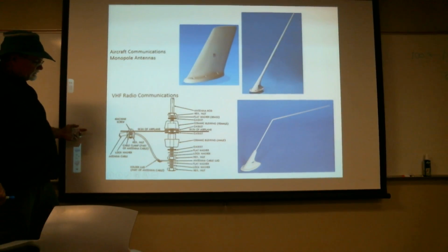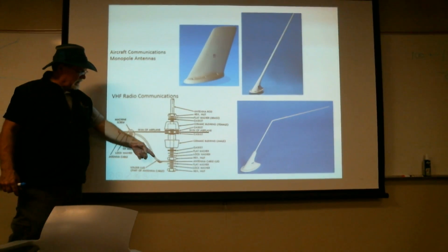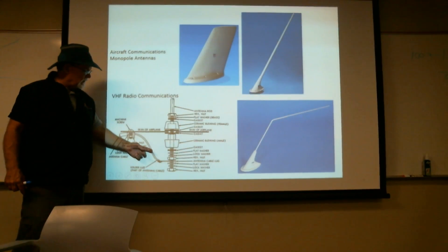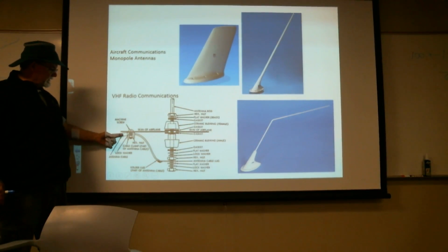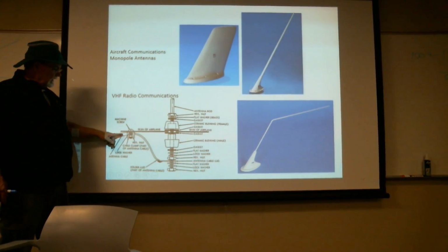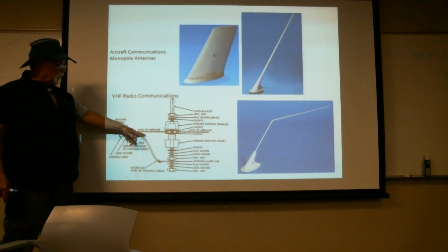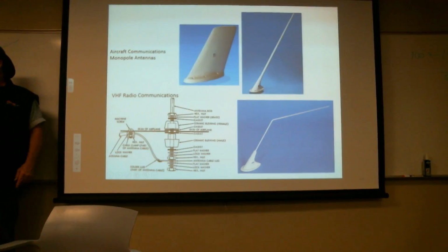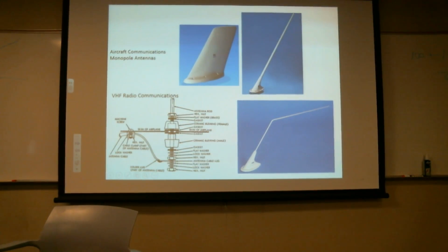And then at this point, you're going to have one lug of the monopole coming in here, the other lug of the coaxial, and they don't show this, but there needs to be a balun. The other lug of the balun would then connect to your ground plane. Okay, they don't really show that as a balun, but it needs to be one.